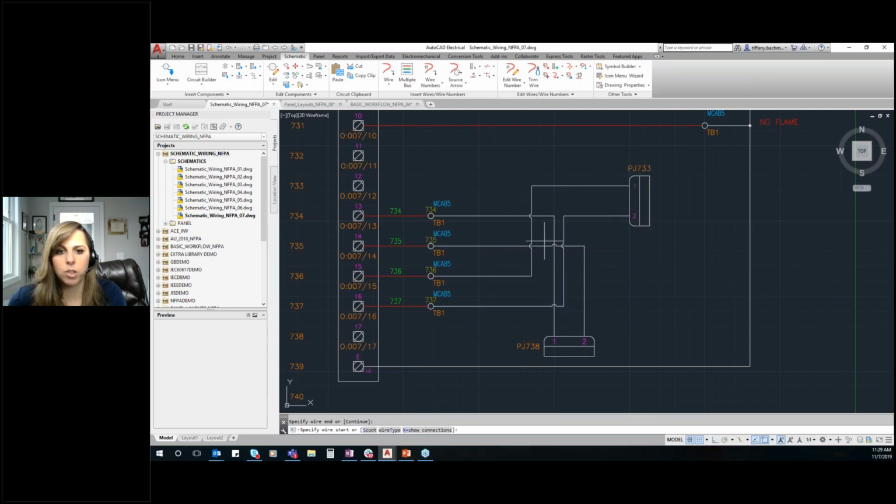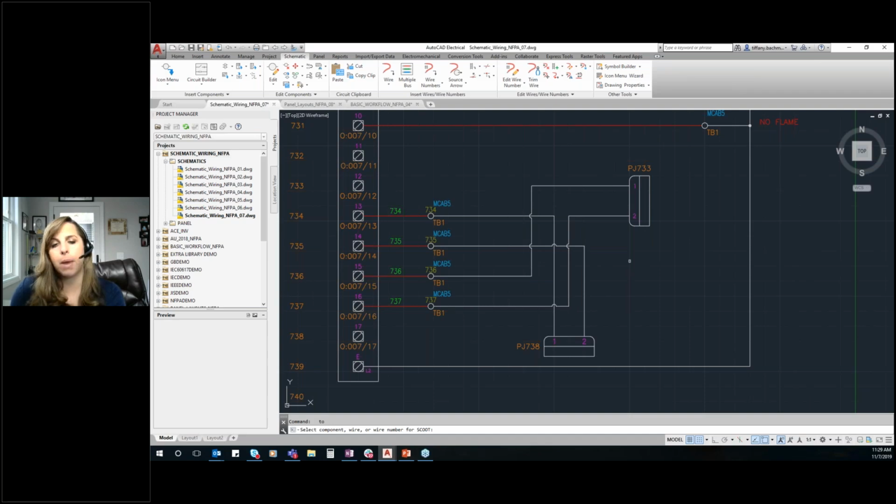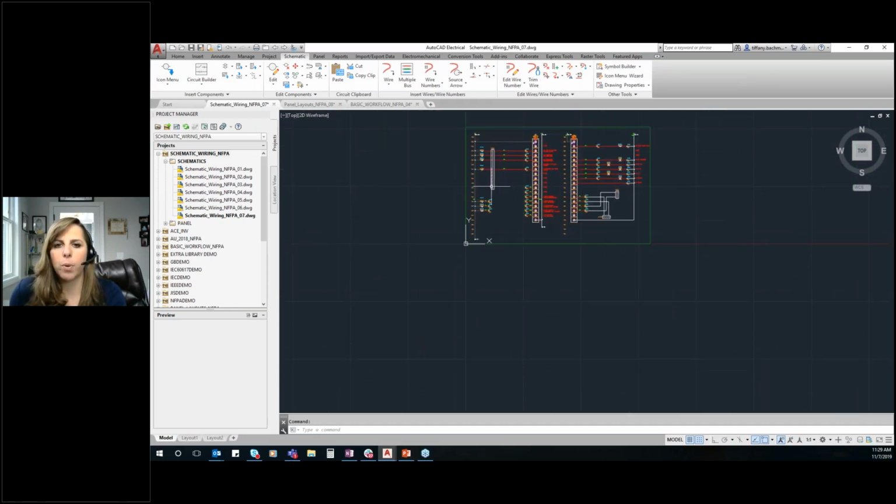And notice it avoided collisions. It wasn't going to run into this one, take the same path. It jumped over it, and it moved it. Now, we do have commands like the scoot command, where we can execute that to have it move. You can move it completely outside, or just shift it over a little bit, but that's only if you want to work on where those settings are. It will always do all of that avoidance for you, and you don't have to remove things and adjust them. So that's the beauty of the collision avoidance and point to point.